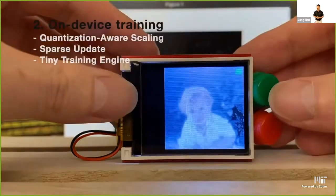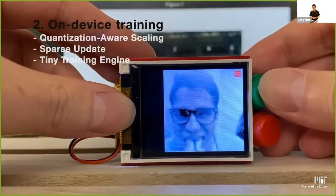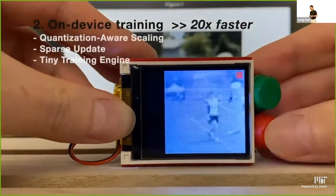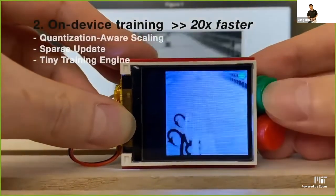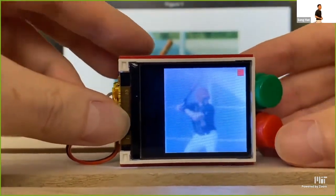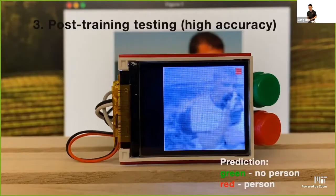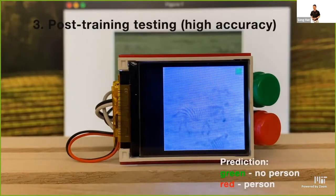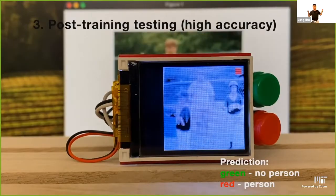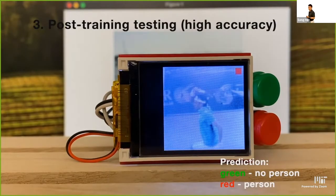Then we apply on-device training: we press the button, green for no person, red for person, to manually input a few labels. The back propagation is done locally on the device, and we do a couple of iterations. Then let's see the classification result. Person in red, no person in green, and it classifies them perfectly. There's no Wi-Fi, there's no internet; everything is done locally on this microcontroller.